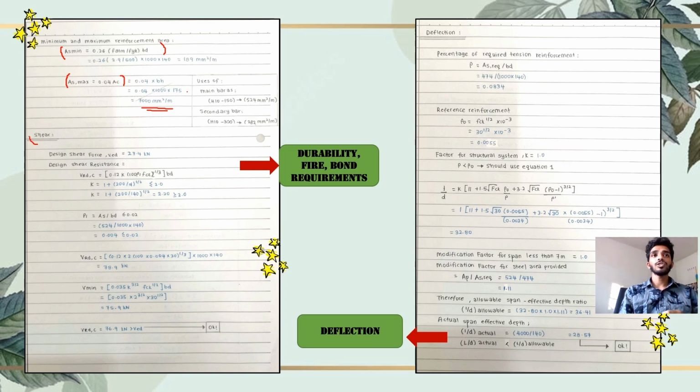And we're going to find out the shear force. The design shear force is VED, and what we were able to get is 27.4 kilonewton, which we previously got in the sketch of the diagram. And the design shear resistance VRD,c is equal to, using a specific formula, we get an answer of 2.20, which is more than or equal to 2.0. So as we can conclude, if it is above the limit, we have to use 2.0 compulsorily. So we will get the answer as 2.0 for the